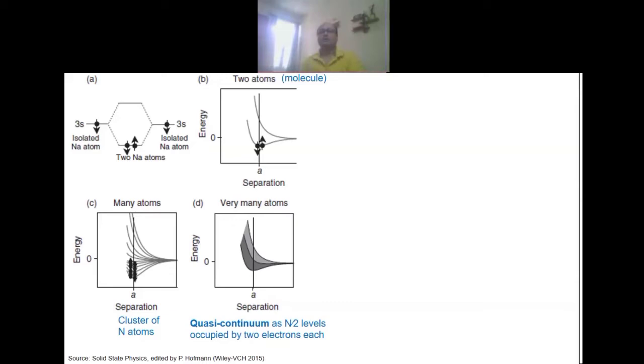Now, if I go once again to that small section of the periodic table, you can see that if we take gallium and arsenic, whenever you make the gallium arsenide compound semiconductor, the gallium atom has 3 valence electrons and the arsenic has 5 electrons. So when they make bonds, they are asymmetric in nature. But ultimately, in total, they have 8 electrons, already fulfilled. But because of this little difference in the number of electrons in the valence band, they have some little polarization.